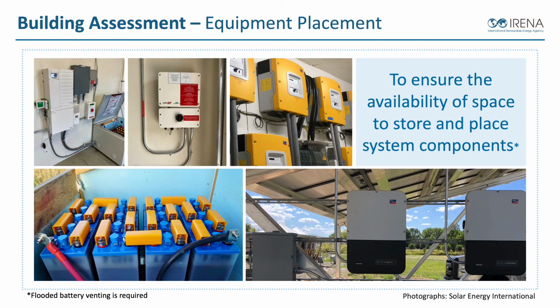The other thing to think about, some of these inverters are designed to be outdoor rated and can handle the elements and the heat and the water and the snow and the cold. So some of them can do that. Some of them are designed to be indoors and need to be protected from those elements. And batteries as well need to be considered. Batteries don't like big temperature swings. And so all batteries are going to have a minimum and a maximum temperature range. Lithium-ion batteries can be a little even trickier.